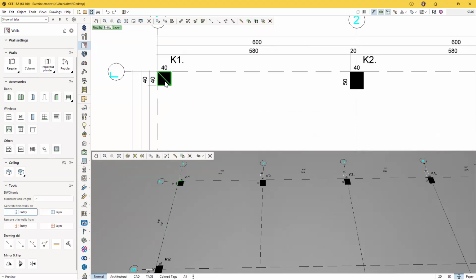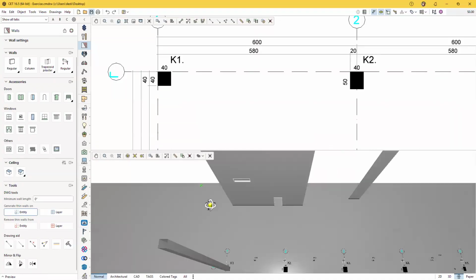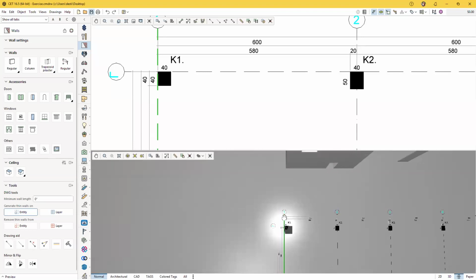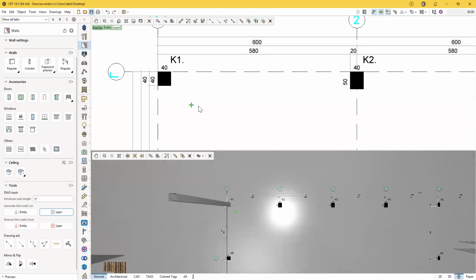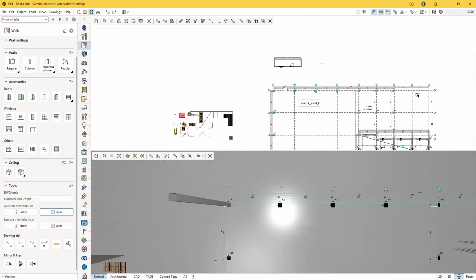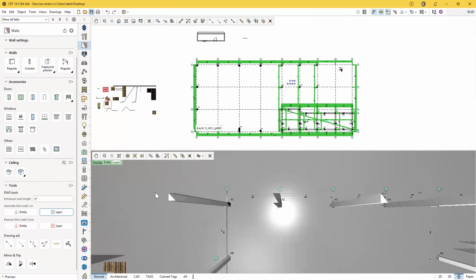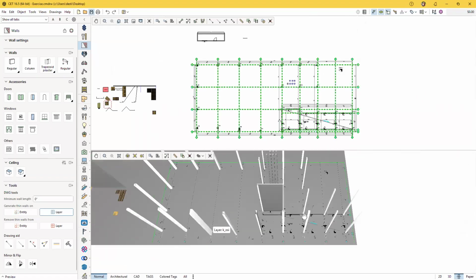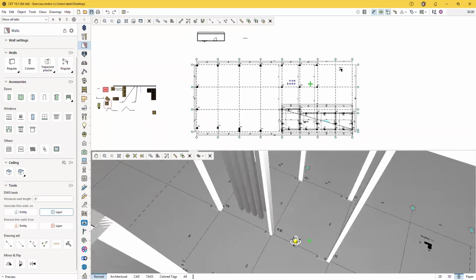So let's say that I have this column right here. I can left click on it. And when I left click on it, I will get these thin walls that are placed all the way around. Now notice instead of being a solid column, I have 4 walls and then I've got this center wall as well. If I try to apply this to a layer, so here we go, here's all of those columns. If I have a CAD plan that was designed really nicely where all of my columns are on a nice, beautiful layer, I can use this tool to apply those thin walls to all of those columns.